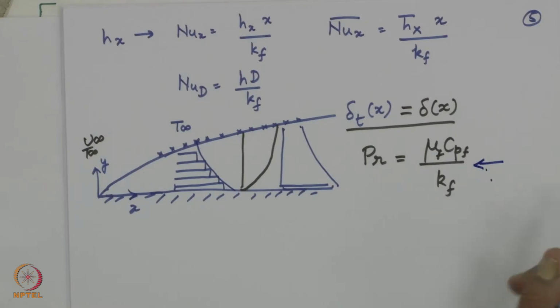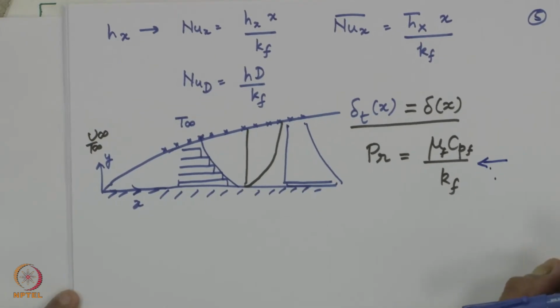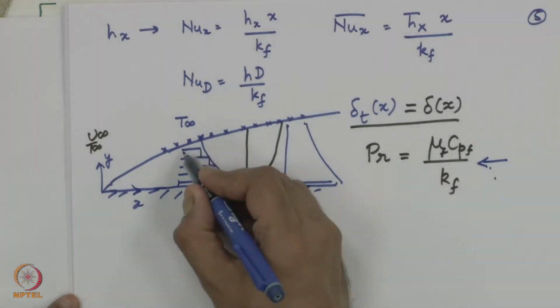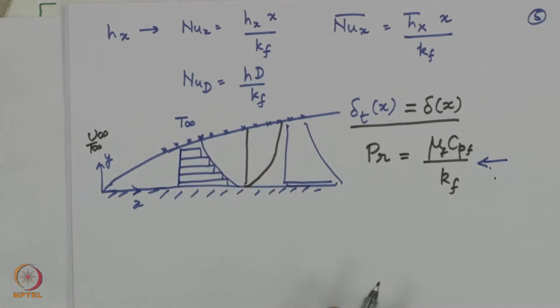In the last module, we ended with the idea of Prandtl number, which is a very important non-dimensional quantity with respect to heat transfer. Prandtl number we said is given by this formula, mu Cp by K, and it decides how effective momentum transport is vis-a-vis heat transport. Both these transports, of momentum and of heat, happen because of certain physical properties of the fluid.